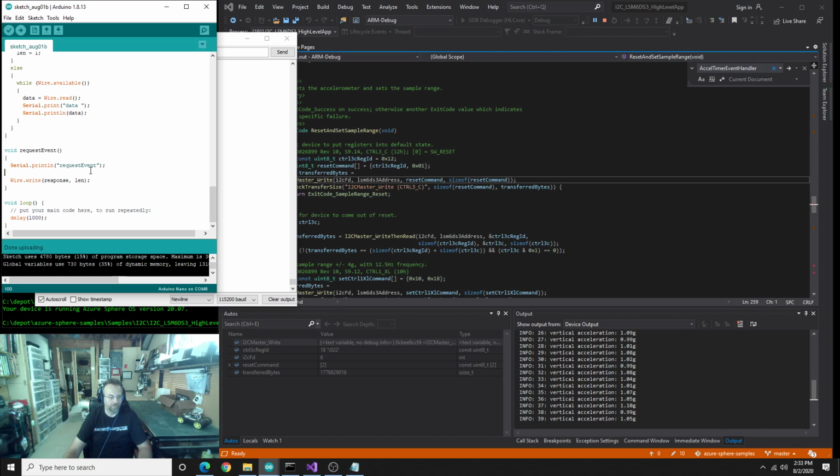One other thing that's kind of fun is to talk about the timeout. So let's do that real quick. Just when you thought you were done, right? So here's some code that basically takes about 3 seconds to run on an Arduino Nano. And we do the print T because otherwise it could get optimized out. So this will take about 3 seconds of looping to calculate some value.